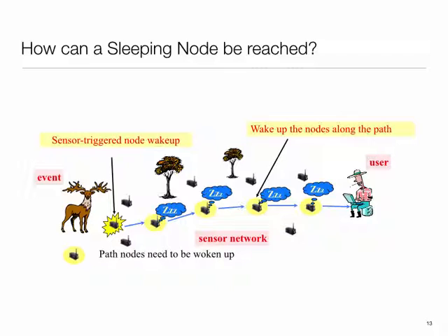There are several ways you could approximate this. One is that perhaps it has some sort of lower power radio, often called a wake-up radio, and it continuously listens on that, and when it sees something there, it wakes up the main radio. But usually that strategy doesn't work out very well, because we're talking about short range stuff.